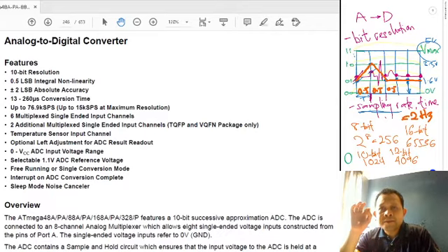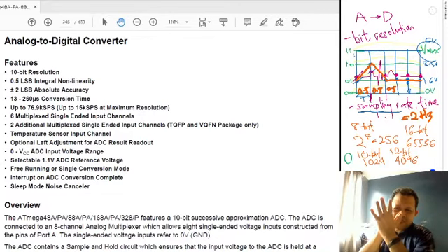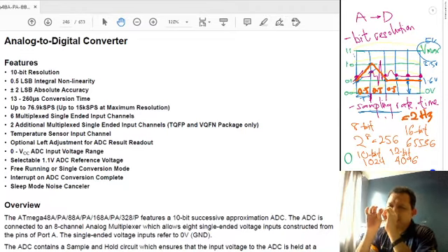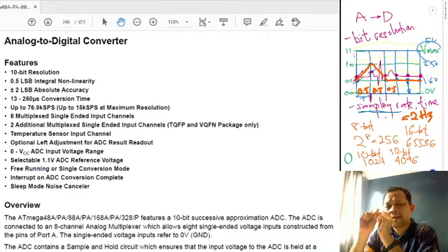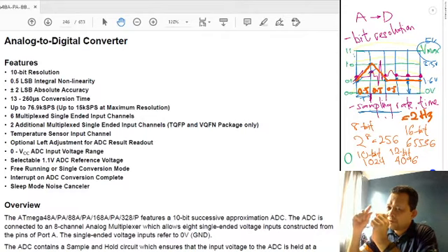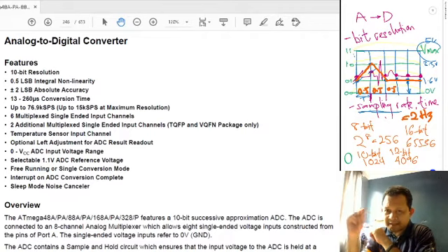Because it is almost very close to your original ECG signal, right? Even if you zoom in very deeply, you can see some levels might not follow the actual analog voltage, because analog voltage is very pure. But when you convert to digital, it will definitely fall somewhere in between those quantization levels.